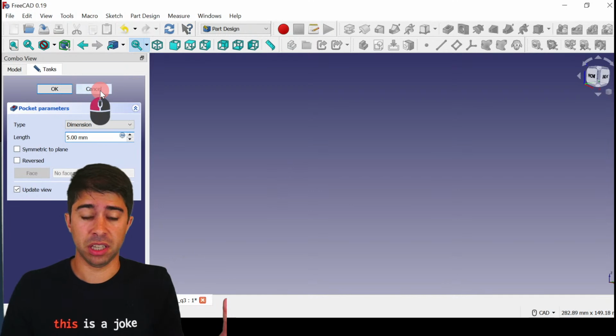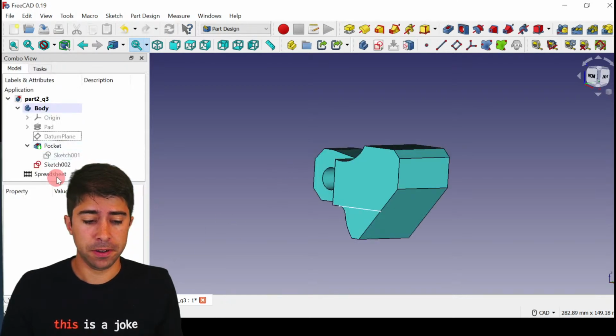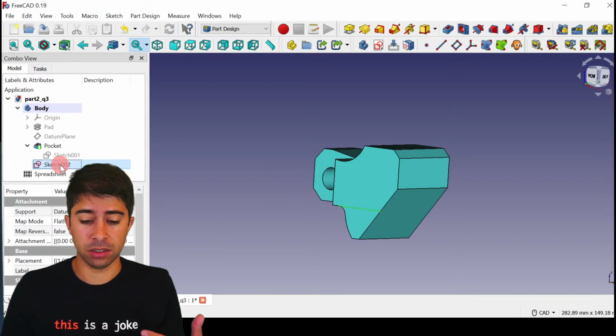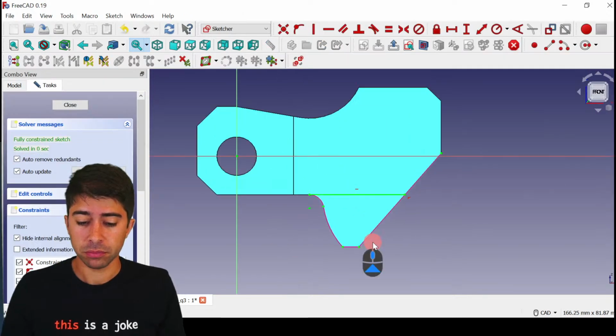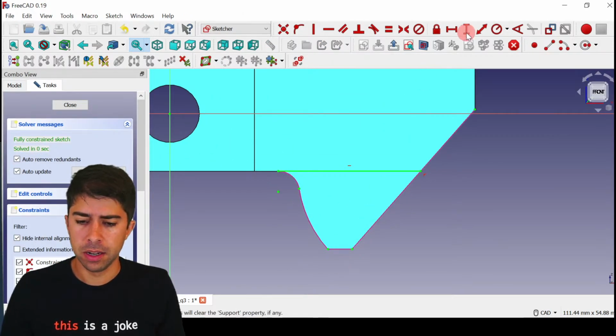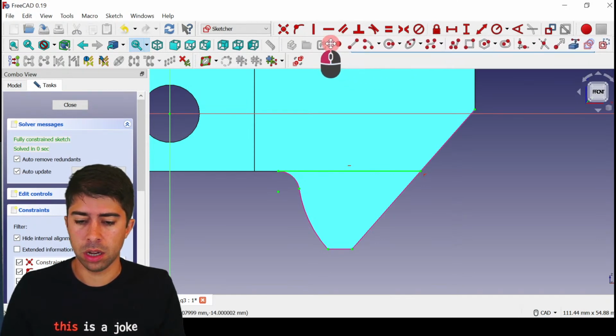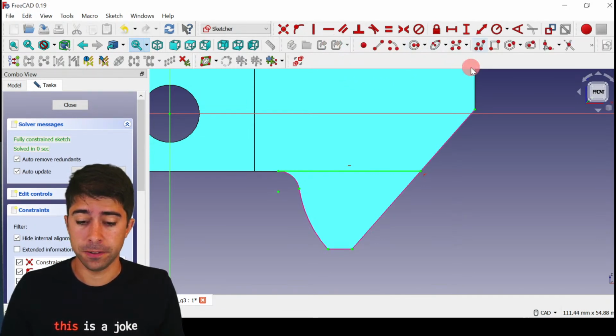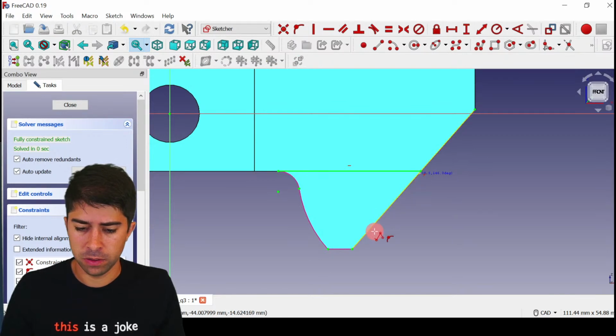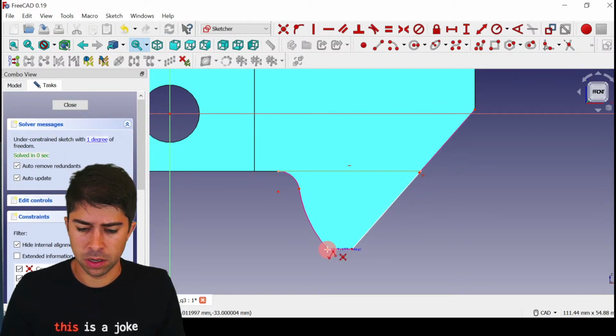It just doesn't do anything, so it's not working at all. So we need to close this sketch. Even though those purple lines are there, we need to trace over them with actual lines. So we're going to go over there, over there, over there.